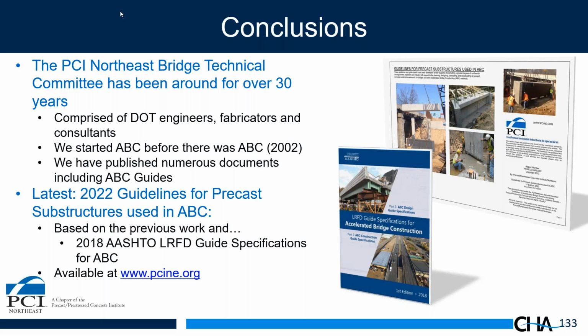The answer is yes. The key thing on our committee is we have fabricators in our committee, and we ask them all the time, what's the easiest joint to fabricate? And the key joints are fairly easy to fabricate, and there has not been an issue with stress concentrations and failing of these joints. The research done for the AASHTO guide specification was based on essentially key joints. There are some diamond-shaped joints that have been tested as well, and they perform well.